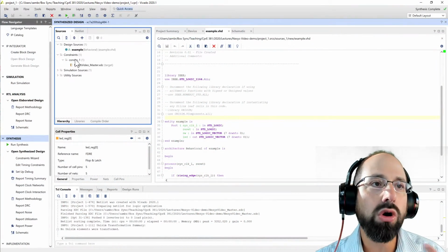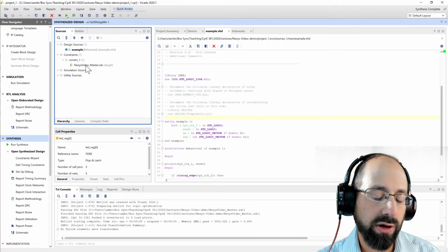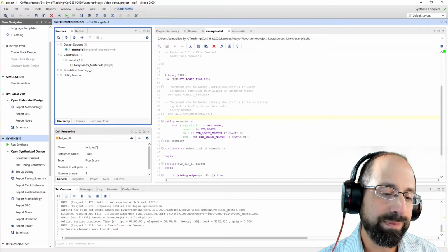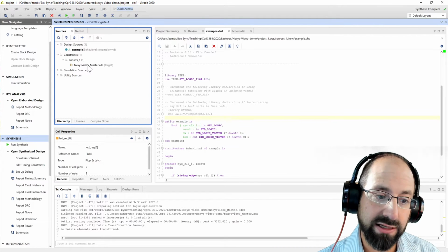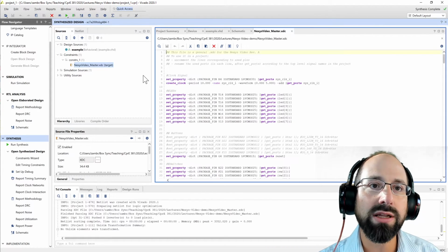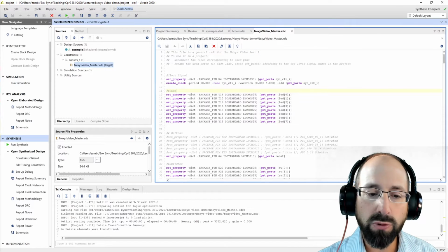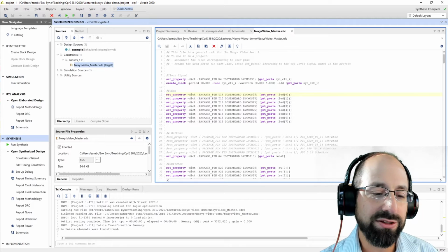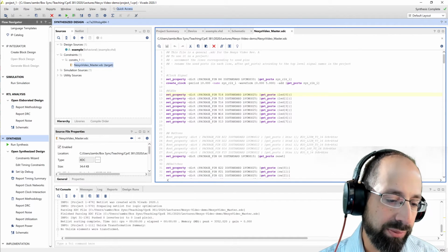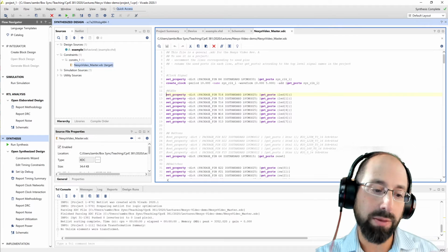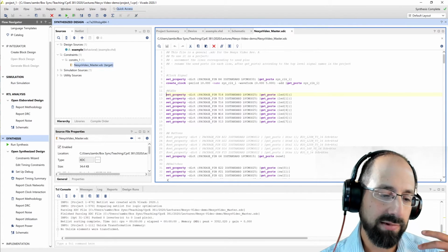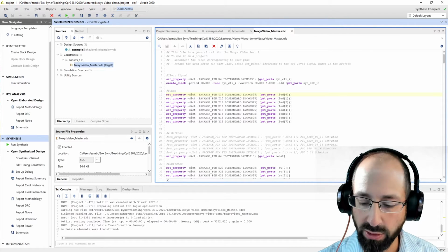There is almost always a secondary source you have to create for your design targets for FPGAs, which is a constraints file. And that file can constrain all sorts of things about the design, but most importantly, what it generally constrains is for certain named signals you have in your design, where physically do they need to go on the FPGA chip? Because assuming you've bought a PCB and you're not separately designing your own PCB as part of this, it has to go in a particular place. It's not your call. It's not your choice where those go.